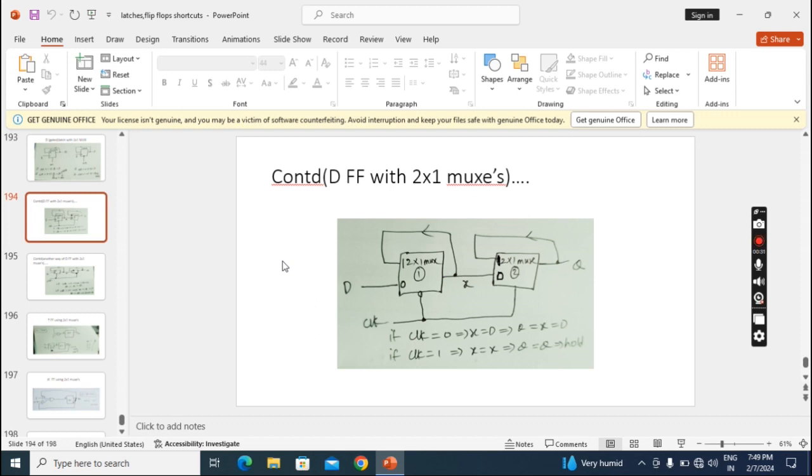I told you in previous lectures, when I compared flip-flop with gated latches, that connecting two gated latches in series will work as a flip-flop. So to implement this flip-flop using multiplexers, I took a negative level latch here and a positive level latch here, and connected them in series. The negative level one has a bubble.